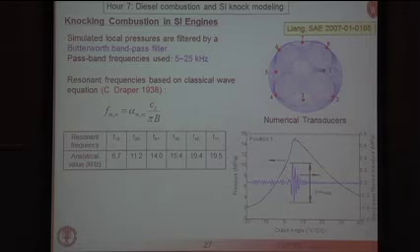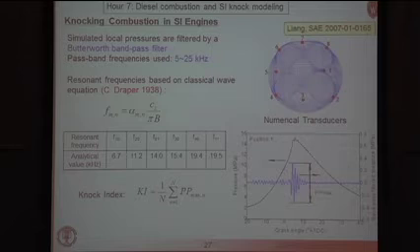We'll see pictures of these in a minute, but there's centrifugal, radial and axial modes that have certain resonant frequencies that are shown here. So if you consider that, you can filter out frequencies below 5 kilohertz and above 25 kilohertz, and this is the resulting figure. The interesting thing here is the peak-to-peak amplitude of these oscillations, and that defines what's called a so-called knock